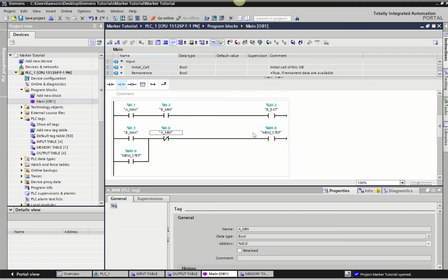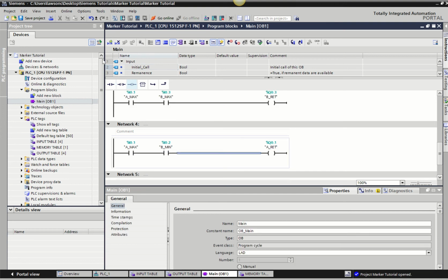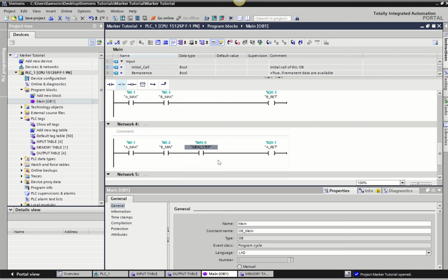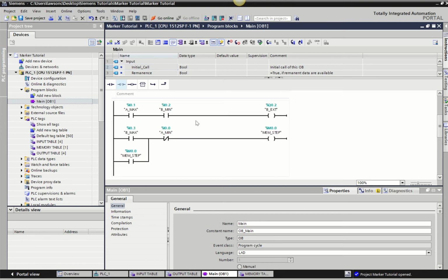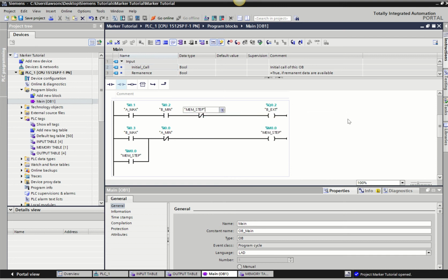What that allows me to do is, B can go ahead and return, and when we get down to here, I can use that memory bit as an input to my system to tell me A can go ahead and return. I also need to put my memory bit on in here, because that needs to influence the line of code as well.